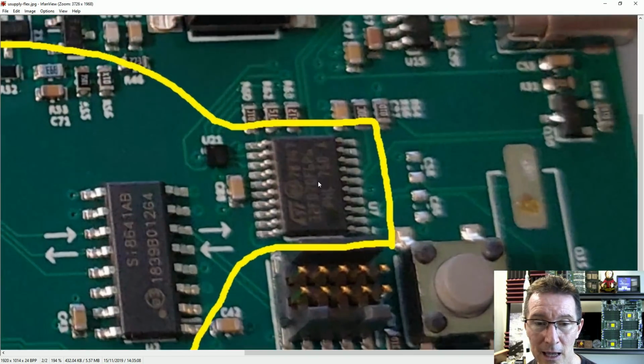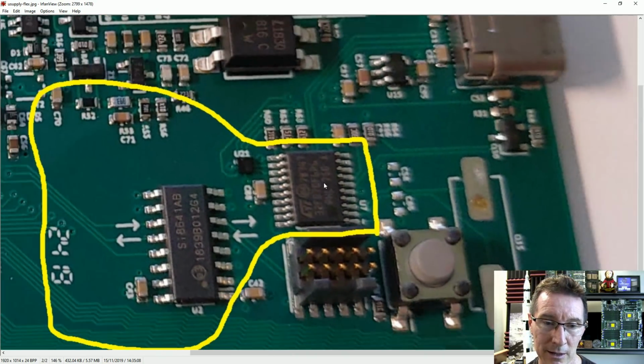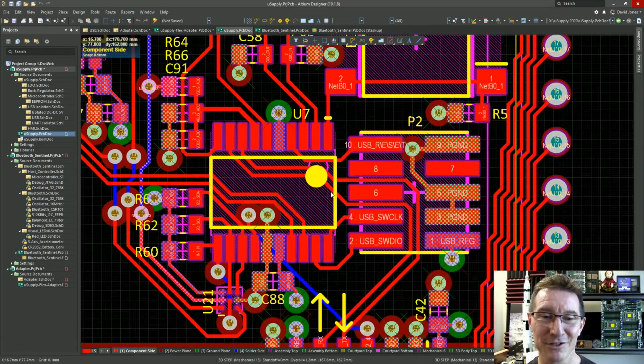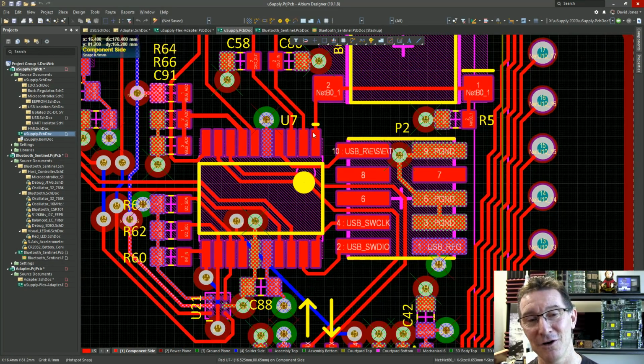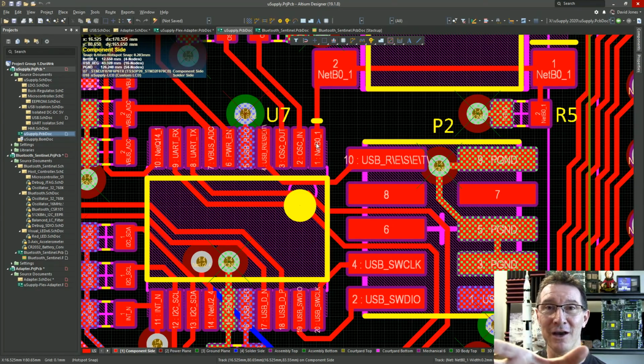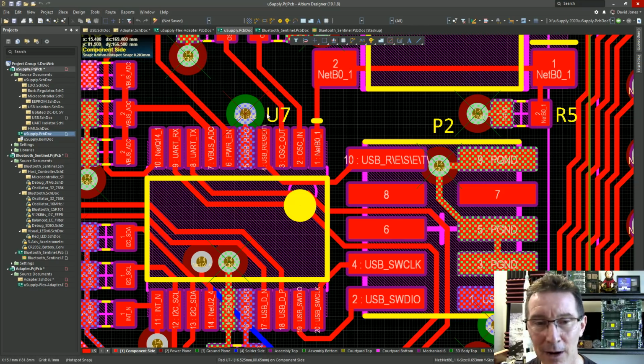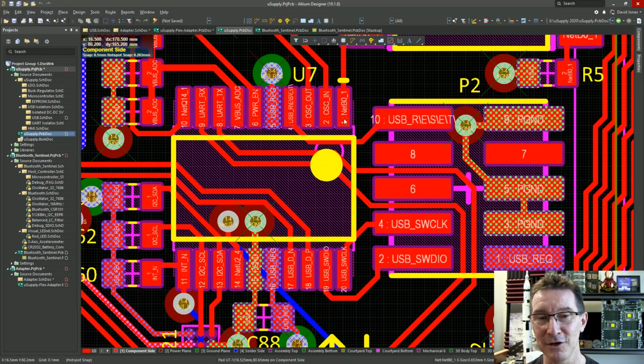Oh, hang on. Have I got pin 1 around the right way? No, pin 1's over here. I was going to come a gutser. Let's just double check on our micro supply board here. Yep, pin number 1 is there. So I need to orient it. Of course, I had it oriented that way. Is that the correct way on the camera? Anyway, I think you know what I mean. If you've been playing along at home, then you know that I was going to come a gutser there. So yeah, need to double check stuff like that.